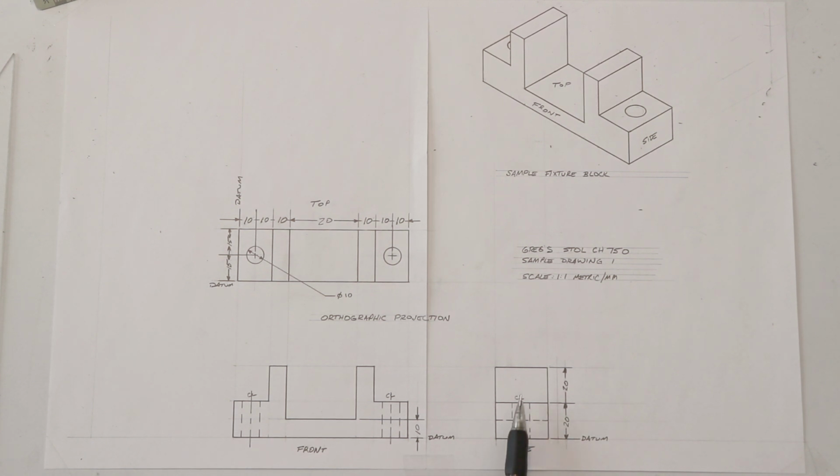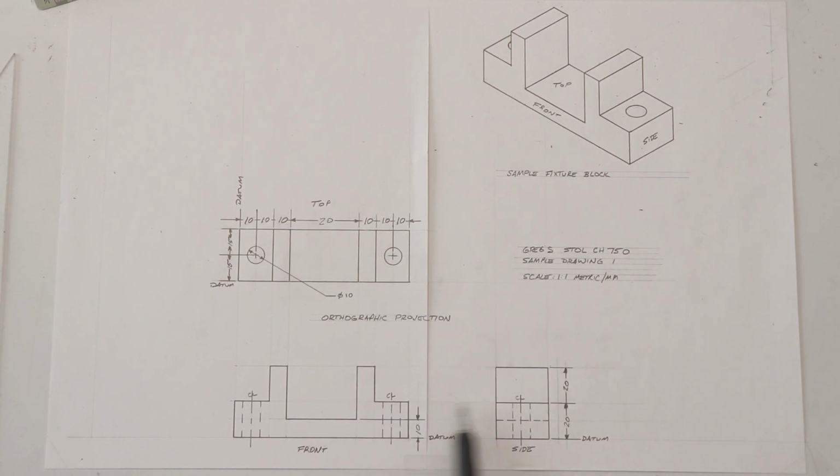The bolt hole is manually drawn in, and then we have a dotted line here which represents this interior feature that you can't see from this view, as well as the dotted line for the bolt holes with the center line. And then we've got a series of cumulative measurements over here. So rather than having 2 line measurements, we have one datum line here, a 20 millimeter measurement from here that denotes the shoulder, another 20 millimeter measurement here that denotes the height of the part. Back over on the front view, we have a measurement from a datum line here that indicates that this interior feature is 10 millimeters thick.